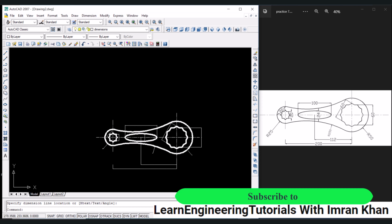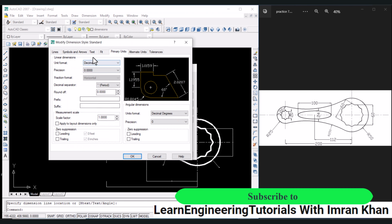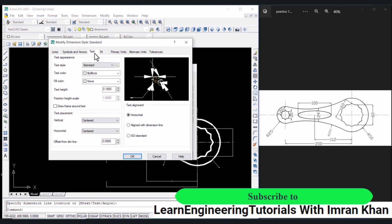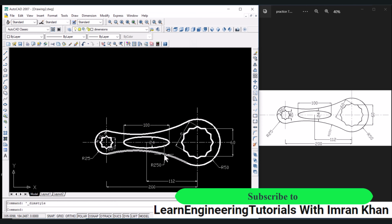Now we have to perform formatting of the dimensions. So click on dimensions, click on dimension style, click on modify, click on symbol and arrows. Let the arrow size be 4. Click on text, let the text size be 6. Click on primary units, let the precision be 0. Click on text, let the offset from dim line should be 2. Click on OK, click on close.